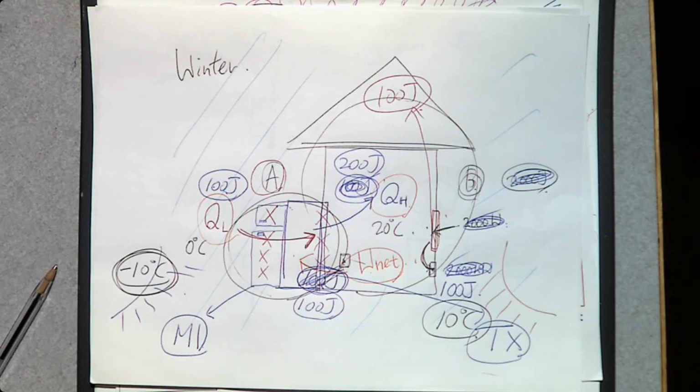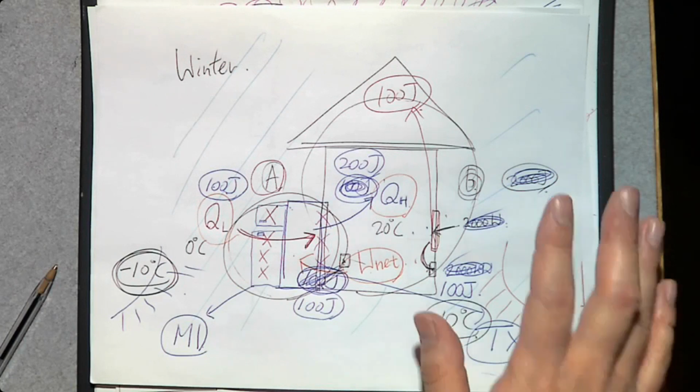And usually when the outside temperature is very low, they don't run the heat pump because cooling outside is not easy. So instead, they run the gas heater. When the outside temperature goes up, but it's still not hot enough, you run the heat pump. So you usually set a threshold temperature, let's say 5 or 10 degrees. Above 10 degrees, run the heat pump. Below 10 degrees, run the gas heater, because it depends on the cost of the electricity, right? Make sense? Sounds interesting, right?